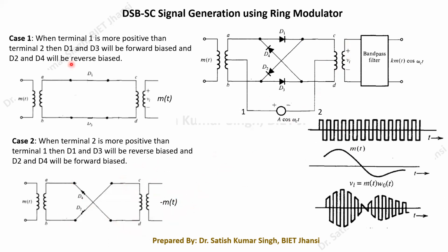So based on these two cases, case 1 and case 2, if you understood the working, one thing I would like to clarify is that these transformers are audio frequency transformers. Whenever we apply this type of square wave of sufficiently high frequency, this transformer will act as an open circuit. There might be a question: why should there not be an induction from this point to this point also? But it doesn't happen because of the design of the transformer.